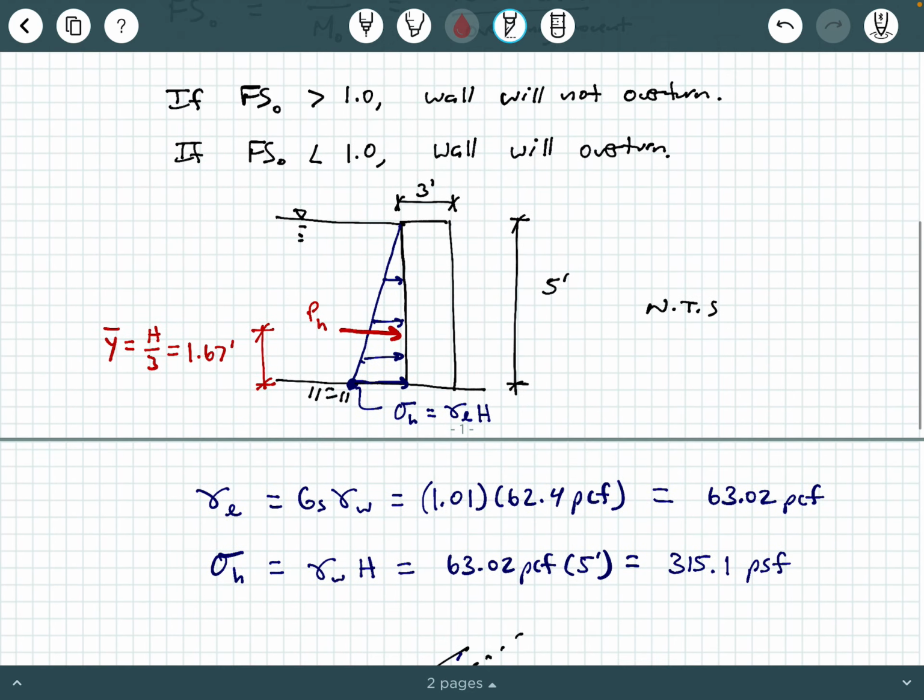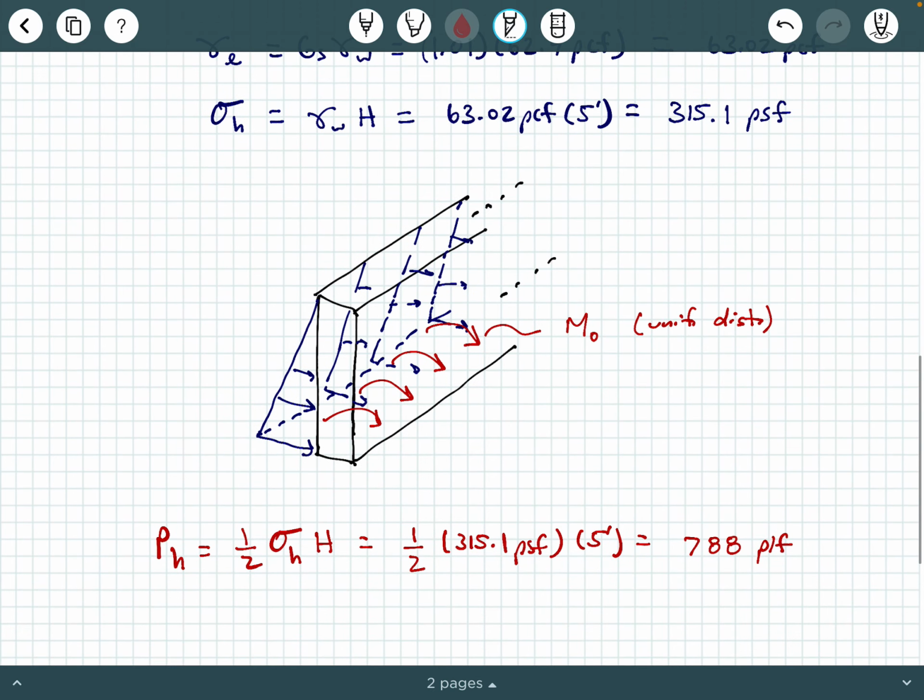That means that you have 788 pounds here, and it's pointing at the wall, of course, just like I drew the arrowhead, but that's a uniformly distributed load coming in and out of the screen, okay? It's coming in and out of the screen at us, but it's directed at the wall. So think of maybe my really bad-looking 3D figure over here. It's a uniformly distributed equivalent load acting on the back side of the wall like this, and here's that uniform load here.